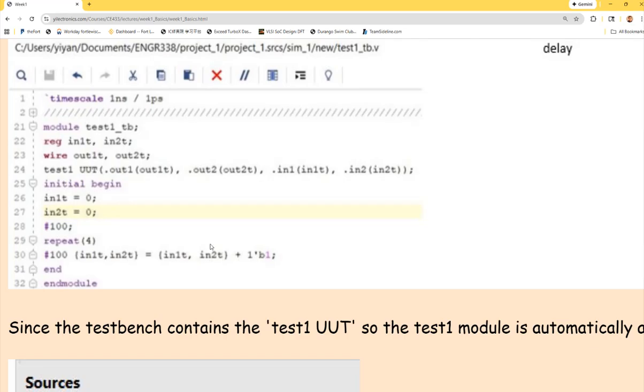So in1, in2, these were individual lines. So these were single binary numbers. But to do the concatenation in this format, it becomes a 2-bit binary number. So in1 here becomes what? If you have a 1 here, it becomes what? 2. So this was 0, 0, and you had a 0, 0 plus 1, it's going to be what? 0, 1.